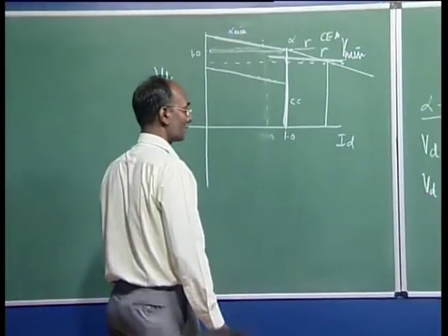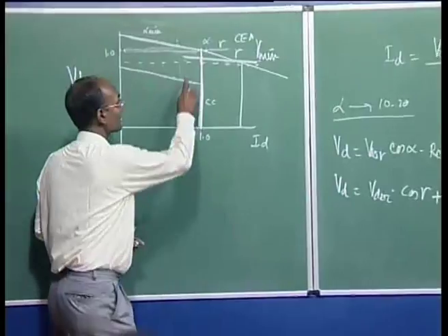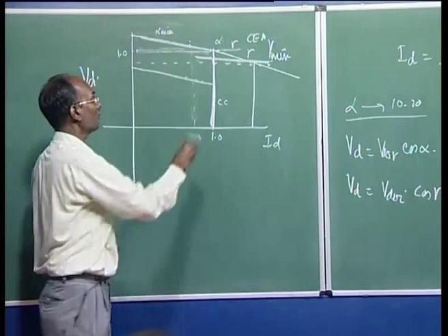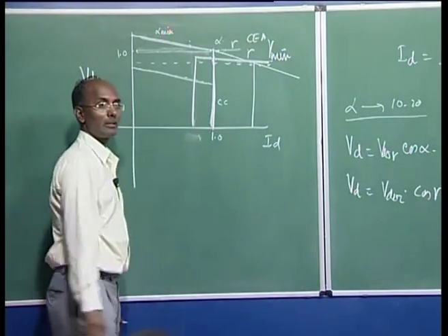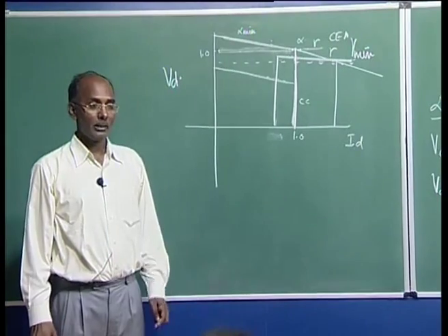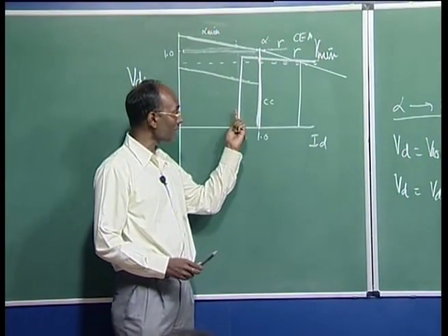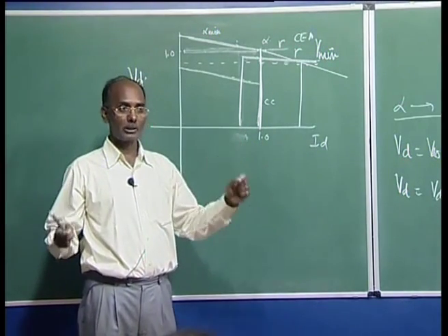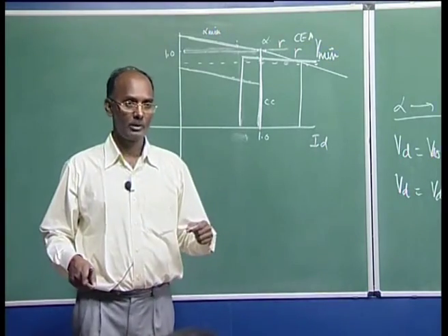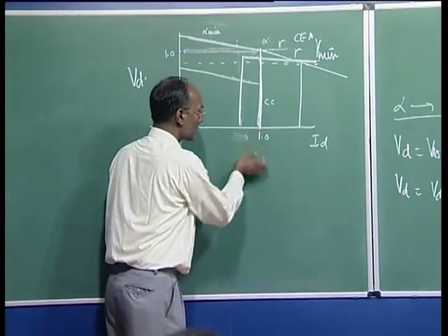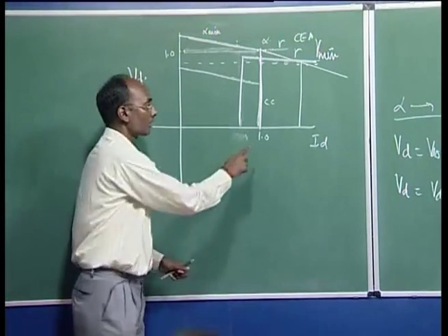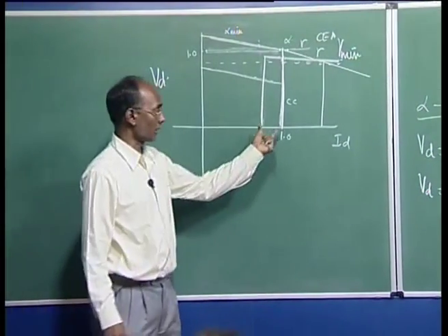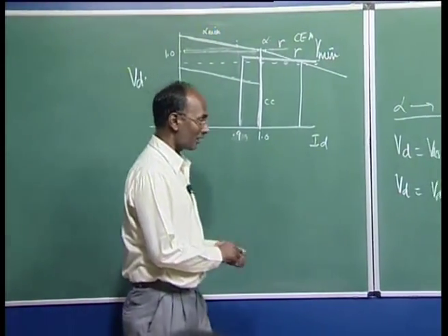So in that extreme condition, what is advisable is that the inverter should also have a current controller, because we want the current to be controlled. We should have another control characteristic here, and the inverter should take it. But we cannot keep the same current rating for both the inverter and the rectifier, because there is a possibility of n number of points of operation, and there will be hunting in the control. So we always devise another setting called the current margin. We take some 10% of the rated value here, normally 0.9 of this per unit.